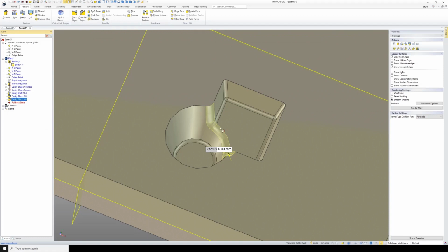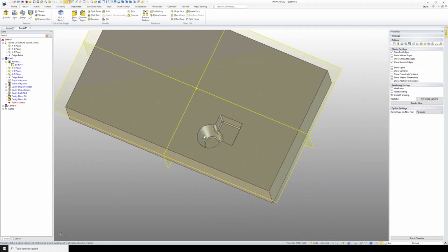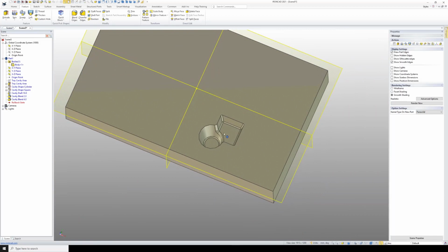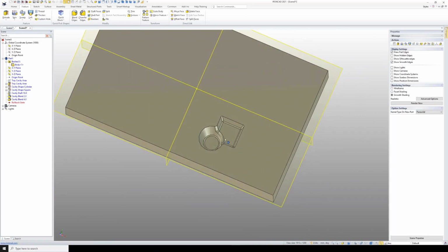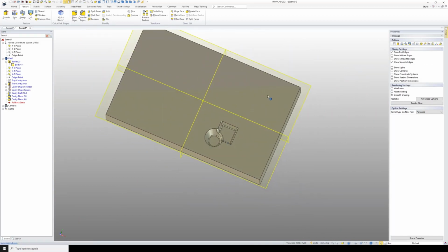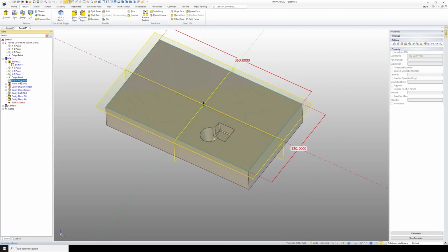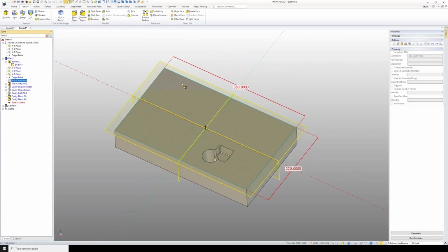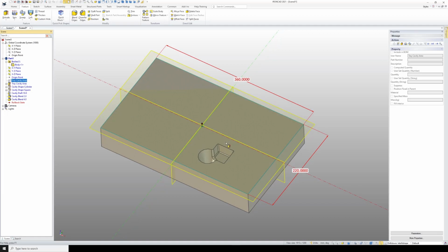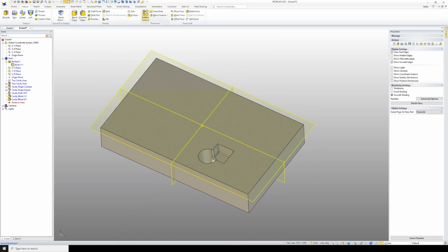And for troubleshooting, right, so I'm happy with my cavity, and I just need more than one, and so I'd like to optimize the use of this whole area, and this is what this is. This isn't defining the area of the tray. This is defining the area that I wanted to pattern, and so the next thing I need to apply here is my pattern itself. And so there's a tool here called pattern feature.